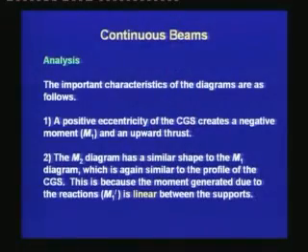The important characteristics of the diagrams are as follows. A positive eccentricity of the CGS creates a negative moment M1 and an upward thrust.